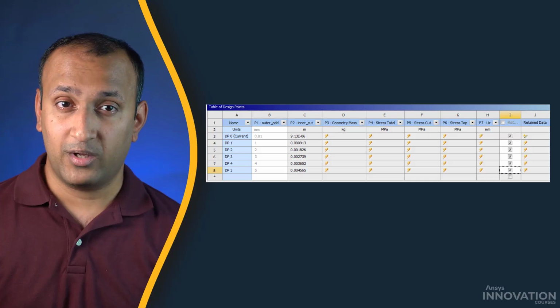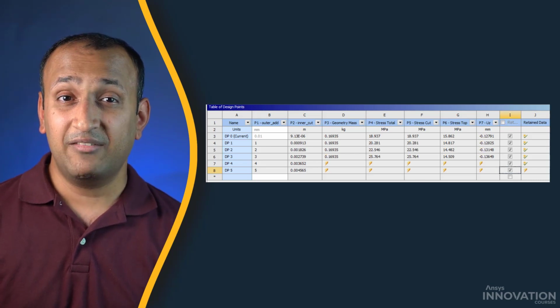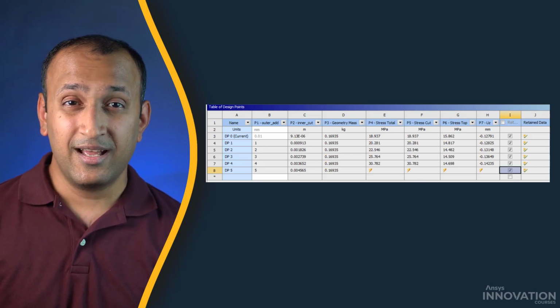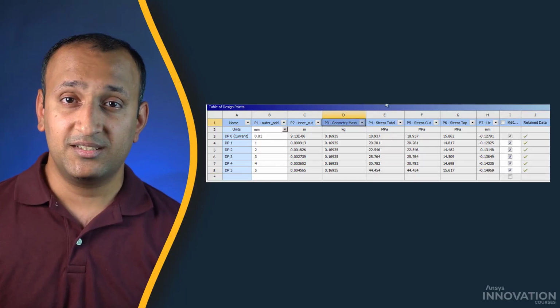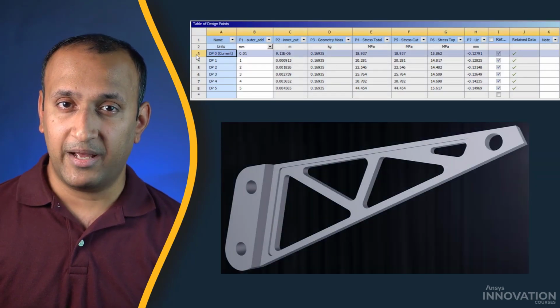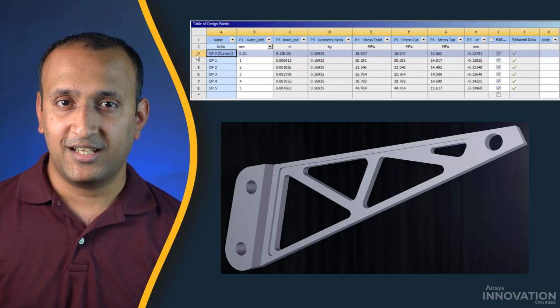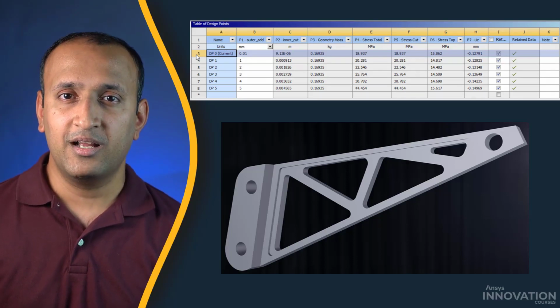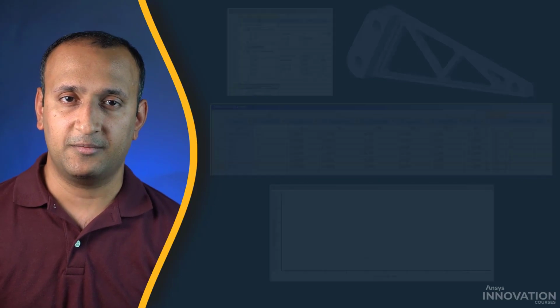We set up the model once and just run it, and it runs 6 cases automatically, giving us insight that the geometric changes aren't linearly related to the stress or displacements, even though this is a linear analysis. We see that the initial design is the best, so if presented with this design change, we can say with more confidence that the design change won't be favorable to the structural response. This completes the demonstration on how to set up, solve, and post-process a parametric model in Ansys Mechanical.